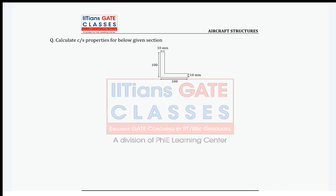Now the main thing comes. We need to find cross sectional properties for this given section, because from here the calculation part starts. So guys, you can see it's an L section. What is the first thing when we find cross sectional properties? We have to define one origin, right? Reference. So this is the reference axis, O, X, and Y.